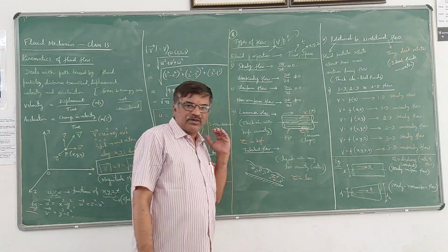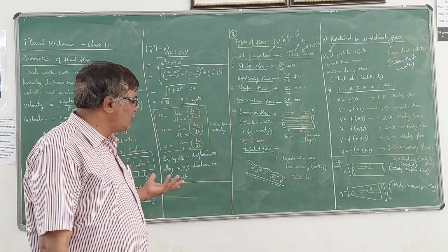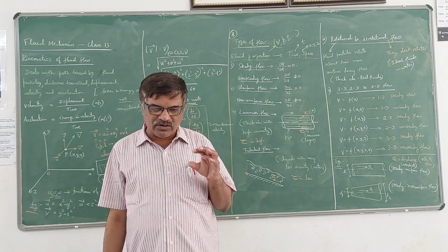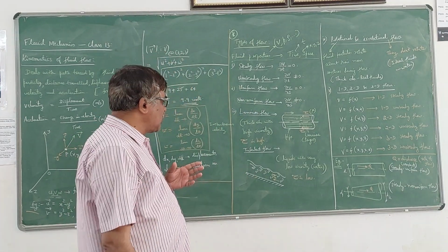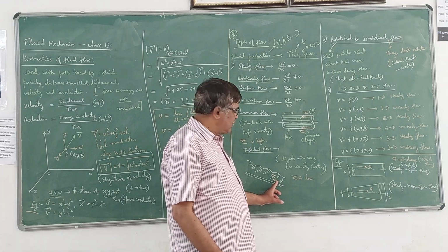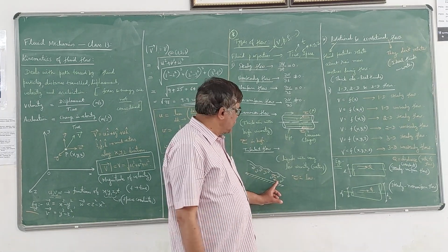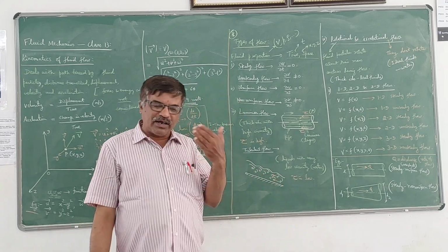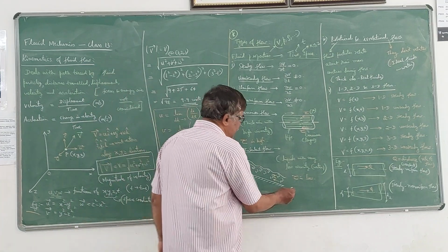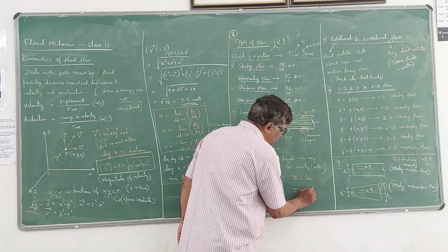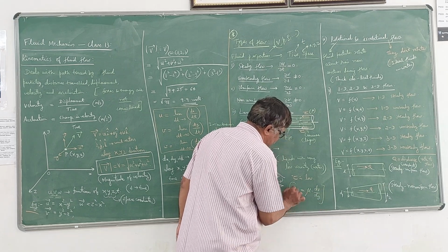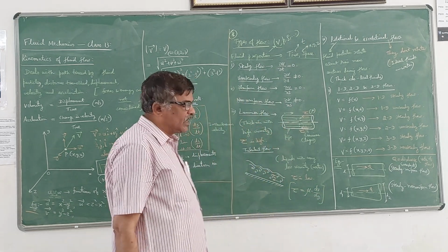Coming to the other way, turbulent flow. In the case of turbulent flow, for example, water, a fluid which has very low viscosity, won't offer much resistance to flow. The tau value is very less, the mu value is also very less. So when mu is less, definitely tau will be less according to Newton's law of viscosity. So we know that tau is equal to mu times dV by dy. This is Newton's law of viscosity, which I have explained in the earlier lectures.